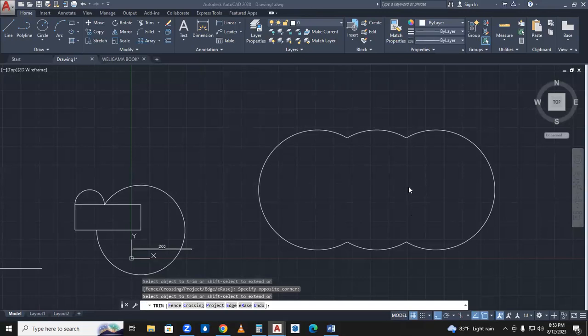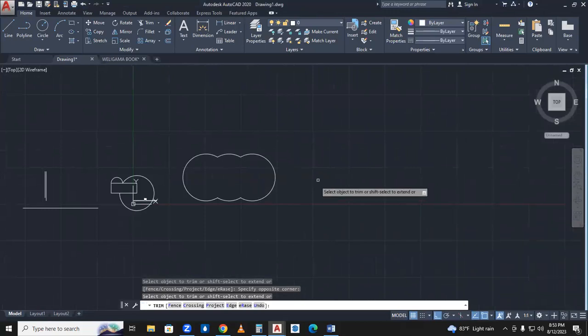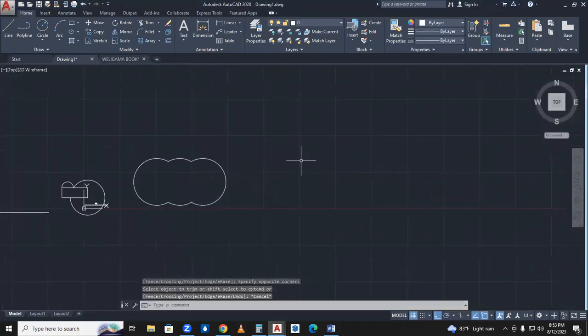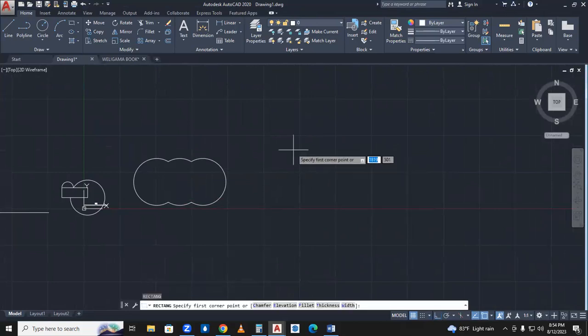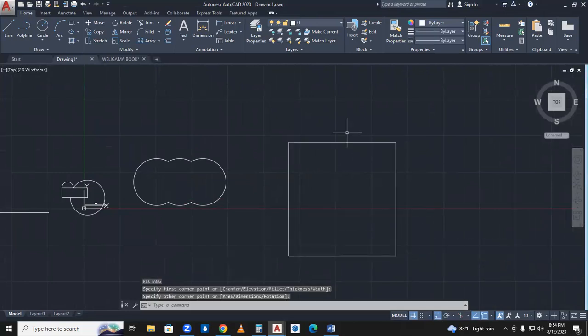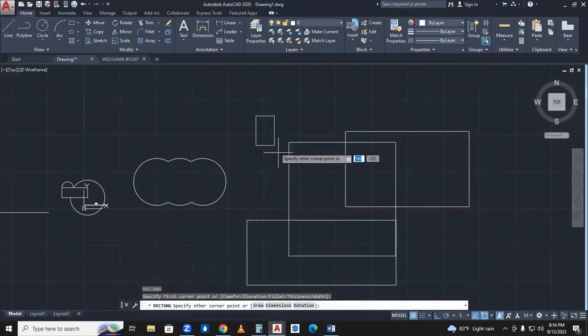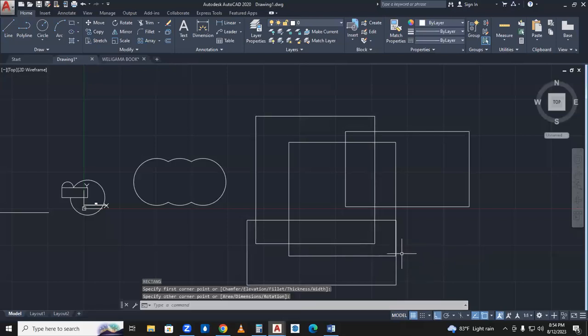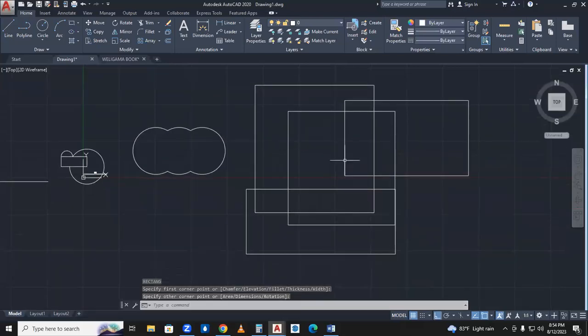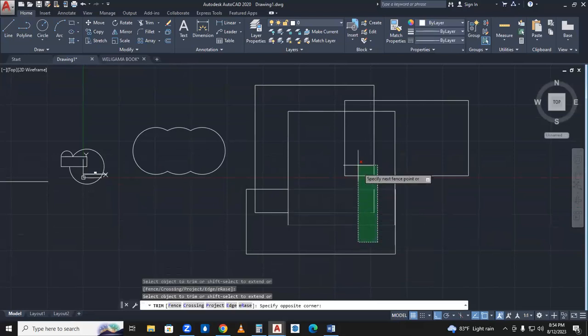Okay. Same. So see another example. So somebody tell the commands. We'll draw a shape. No, I'll draw myself. So I want to delete, let's say, the internal lines. What I do? TR, enter, again another enter, and I'm selecting the lines which should be deleted.